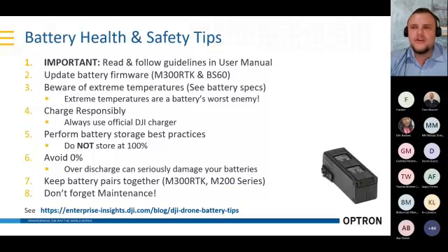And also you need to perform the best practices for battery storage. When it's fully charged, do not store it at 100%, and also avoid draining your battery too much. So ideally the storage level for a battery is about 70%. Also keep your batteries in a good environment, not too hot, not too cold, just a controlled environment. And do not overcharge or over-discharge your batteries. That can do some serious damage, and you won't get as long a life out of your batteries.